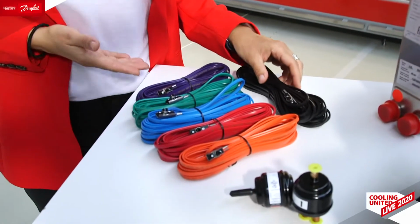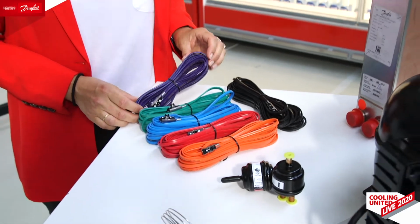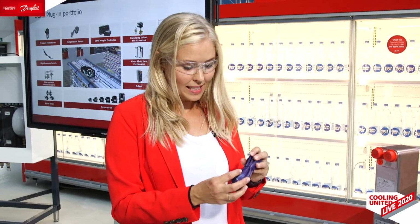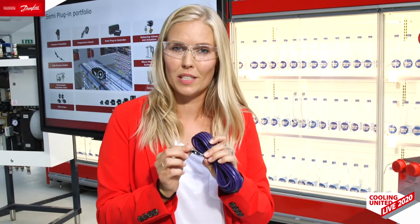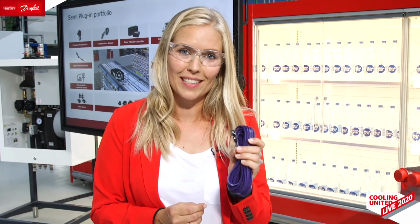Now we have 5 new colors, making it easier for servicing, so that each location of the sensor has a specific color. Besides that, these sensors are mounted with a PT1000 sensing head, securing a very fast response time, but also there's no need for the yearly calibration.